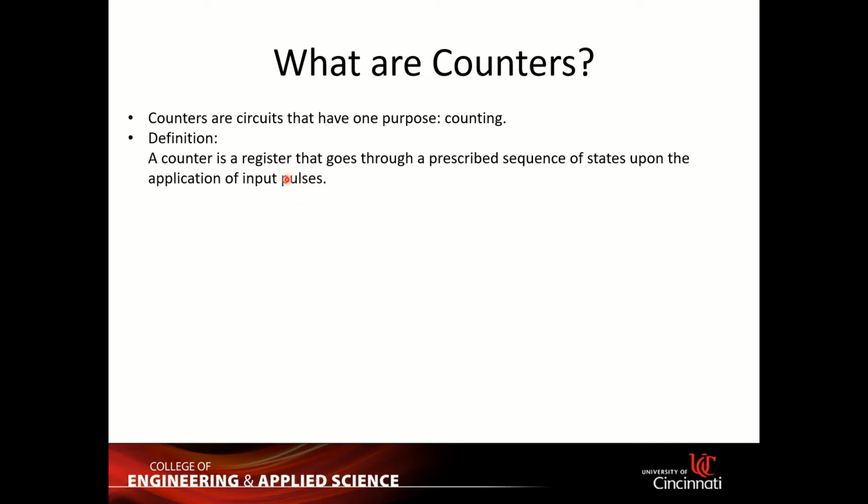Okay, you recognize there are two keywords here. The first keyword is register. That means a counter by itself is just a register, a group of D flip-flops. Each D flip-flop stores specific information. But here the state of this group of D flip-flops will change in a prescribed sequence. You can design a sequence. And the change is upon an application of input pulses.